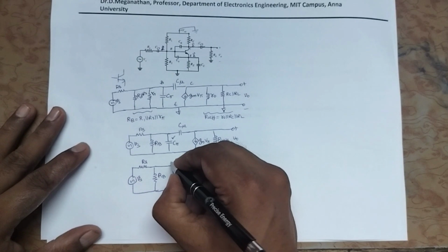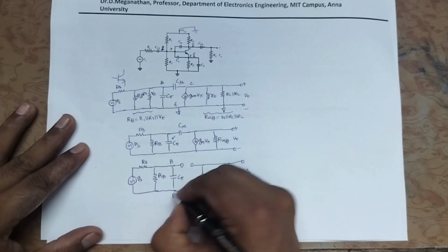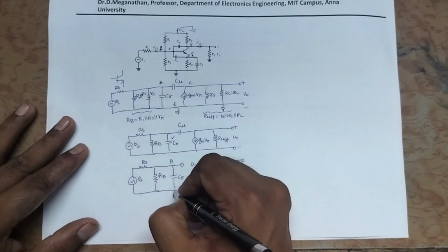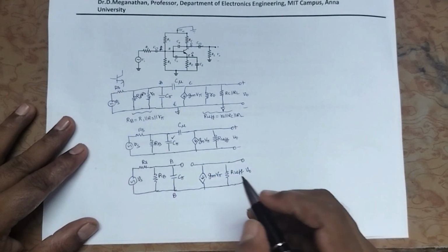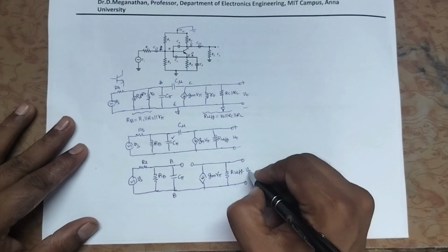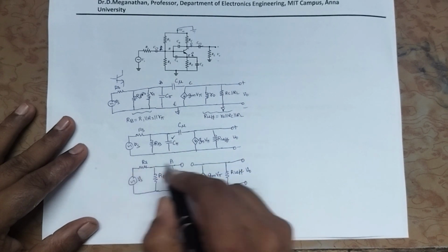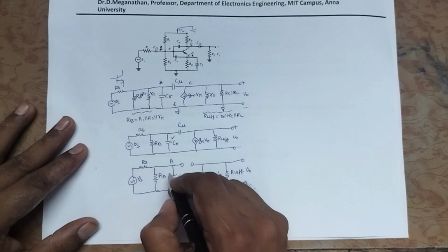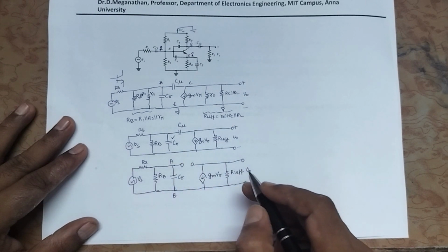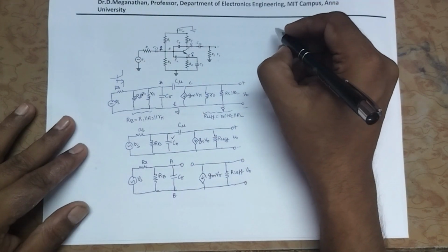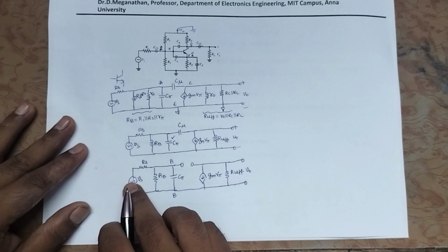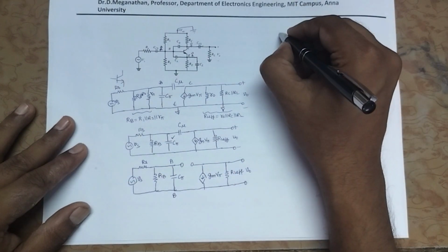This is a capacitor, let us say A and B. Okay, there is no source connected across this capacitor terminal. V naught is the output source, Vs is the input source. These two sources are not connected with the capacitor terminal, so we can null them. How to null it? We know that nulling the voltage source will be shorting the voltage source. Let us ground the voltage sources.